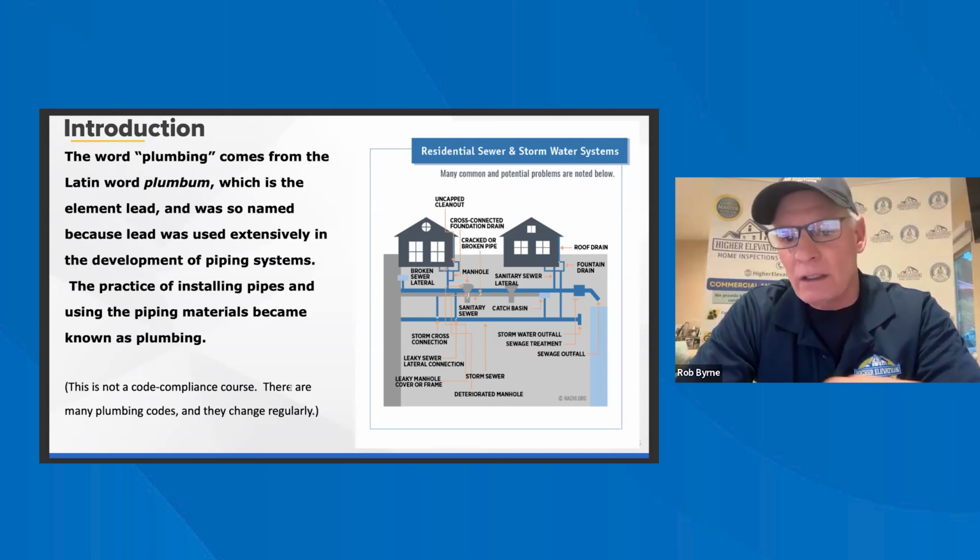So the water would expand, push on that diaphragm, and compress the air, and it'll kind of keep things in balance. Same thing with the thermal expansion tank, and you've got the Watts valve for that as well. Everything to control the expansion of the water.